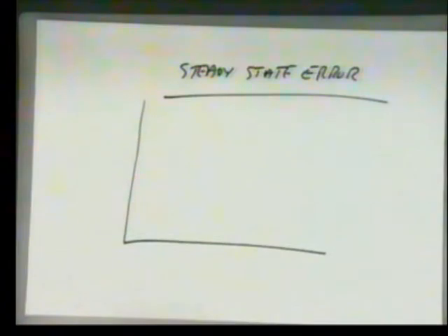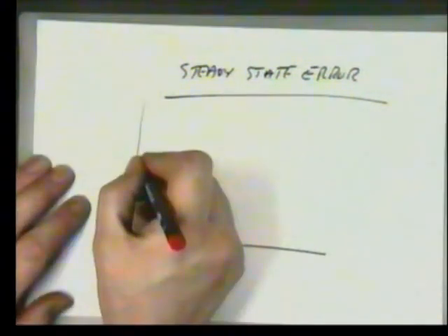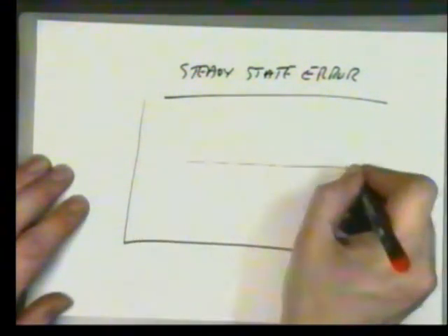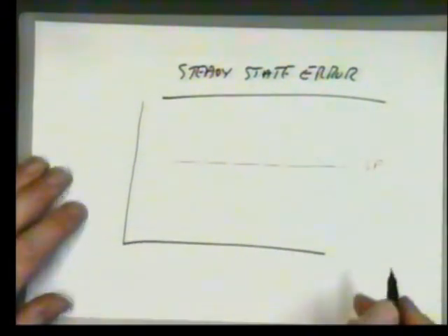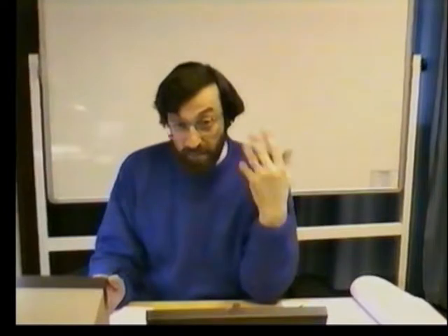There's nothing you can do about it. All proportional controllers will exhibit steady state error, no matter how expensive, how fast it runs. You can't control the outside world. You cannot beat nature. Out there, something will knock you off station. And it's a random event. And it will always tend to drive you a little bit above the set point or a little bit below.